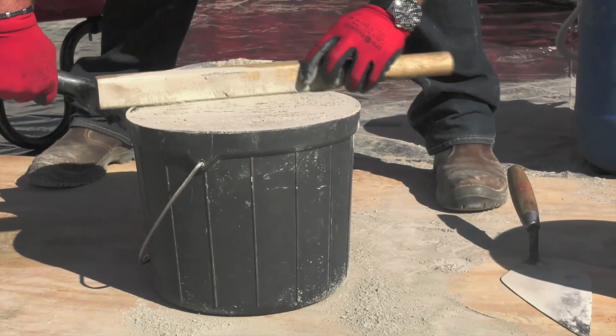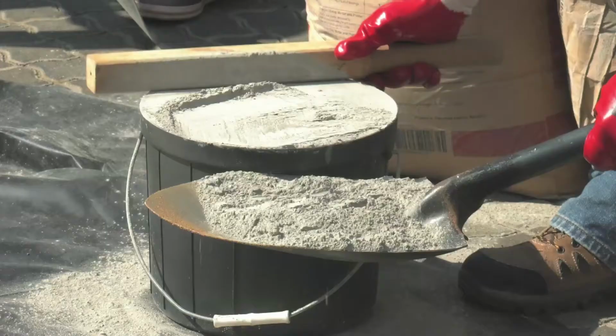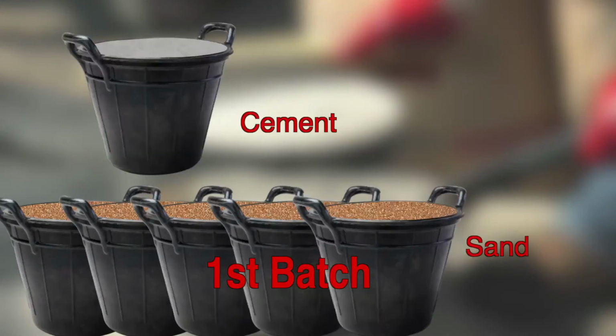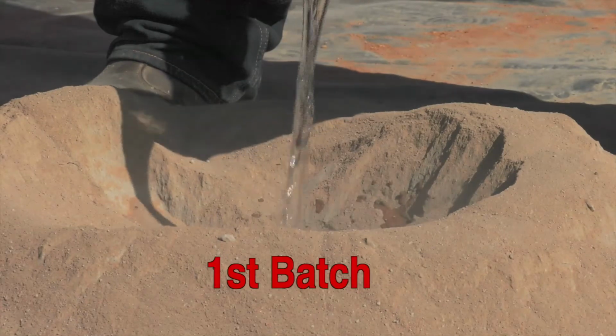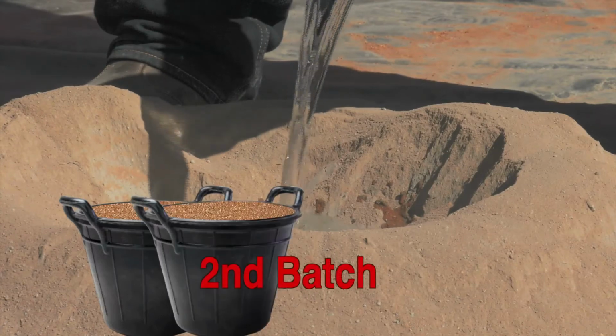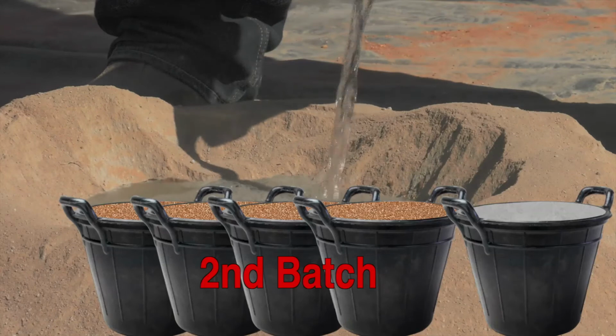In order to find the best mix, you would have to make at least 2 mixes to assess the final outcome. Today, we will start with 5 buckets of sand to 1 bucket of cement and add water as required. For the second mix, you can use 4 buckets of sand to 1 bucket of cement and add water as required.